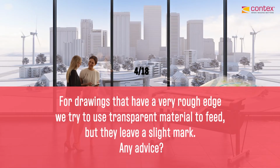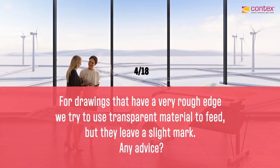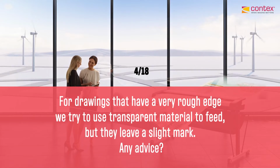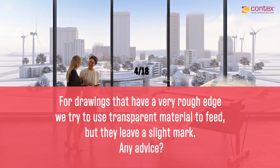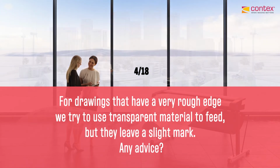So it sounds like there are actually two issues. If he's using things to straighten out a rough edge, then that's going to change the size for the auto sizing. In that situation, I think you would be better served to either pick a fixed sheet size or create a manual sheet size, which you can do very easily. If the normal architectural sheet sizes aren't going to work in your particular case, you can set your own just by typing in the dimensions of the sheet, and you can actually save that as a future sheet size.